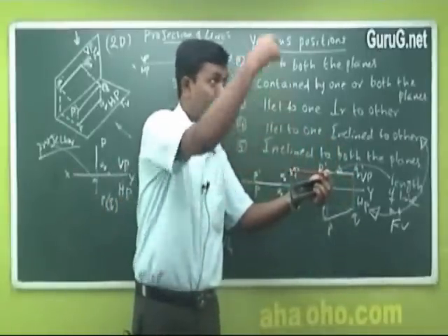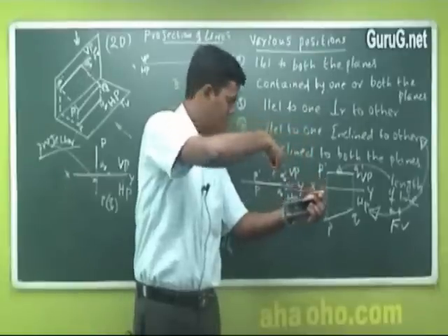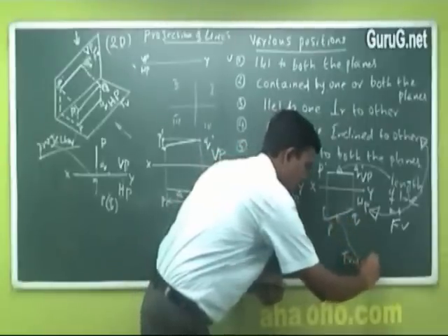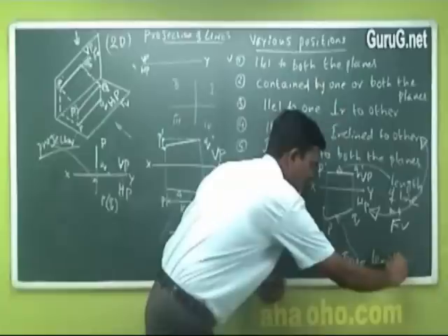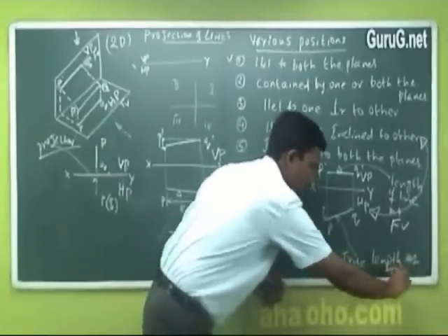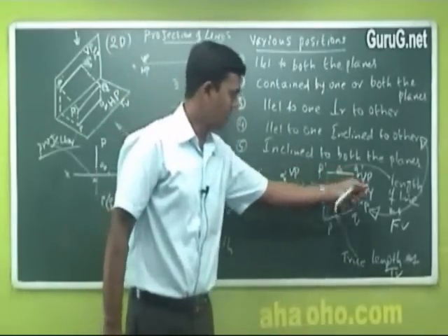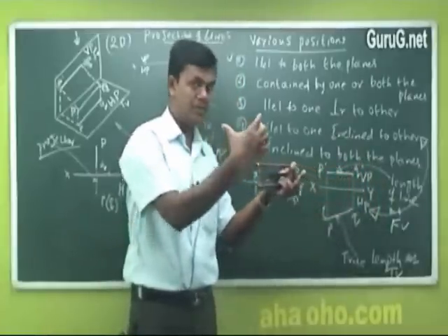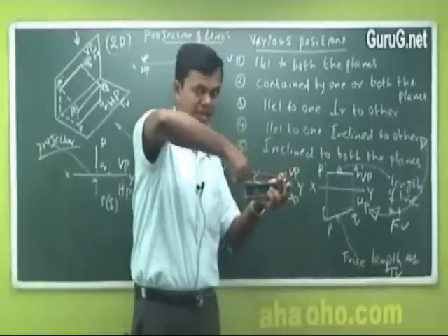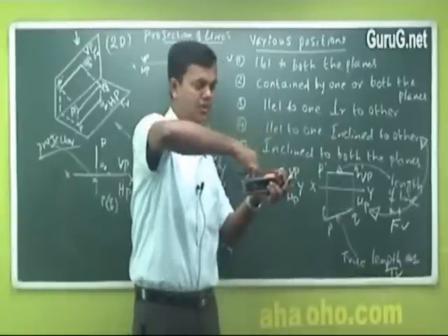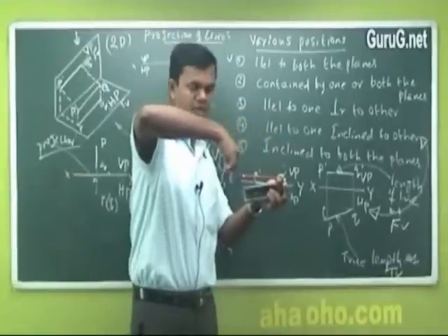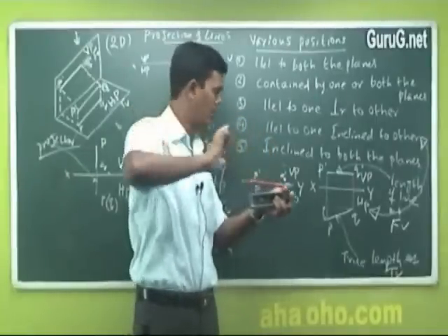Actually it's inclined, but we can see from the top this inclination. This is the true length of the line, length at top view, TV. In the front view it is just the length of the line only. It will be either less or more. But in the top view only you see the true length. Actually it is inclined, but 15 centimeters remains as it is. But in the front view it is not 15 because it is turned, you see only this point and this point. It may not be 15 because it has just come here. Okay, that is the point.